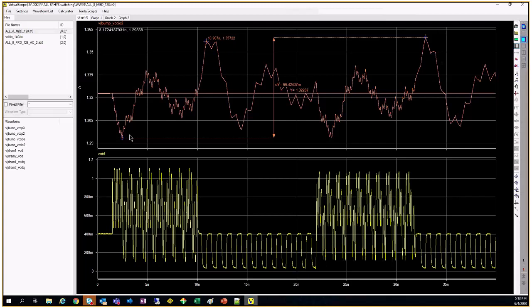This is the switching noise, basically. Peak to peak difference. Every time your chip is switching, there is some fluctuation, and it is causing fluctuations. Why is it called this? Because whatever fluctuation you see here, it affects your signals, the signal integrity. So if you're transitioning from 0 to 1, due to the PDN network, it takes time, right?